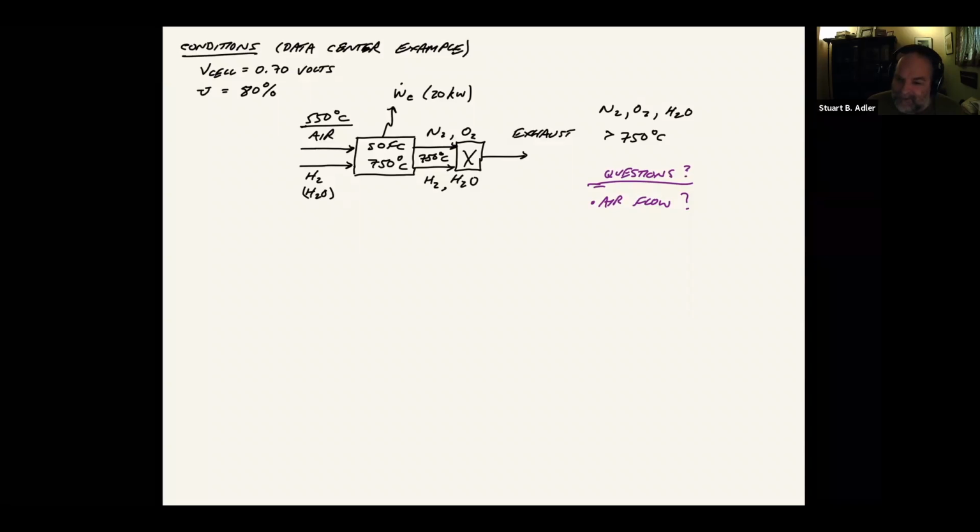We're producing electricity and we're producing thermal energy. And now to get up to 550 C, we have to put in thermal energy, which seems like the opposite of what we're actually seeking to accomplish. Hydrogen is your primary resource. If our fuel cell is operating at 80% utilization, that's basically saying we're wasting 20% of it. Now we're going to waste even more of it in the overall process in order to heat the gases. That lowers our effective utilization of our process below 80%. Is there any way to do this without using any more resources?